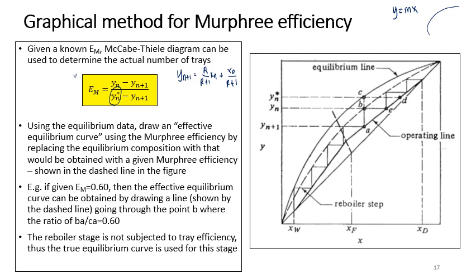Using the equilibrium data, you can draw an effective equilibrium curve using the Murphree efficiency.